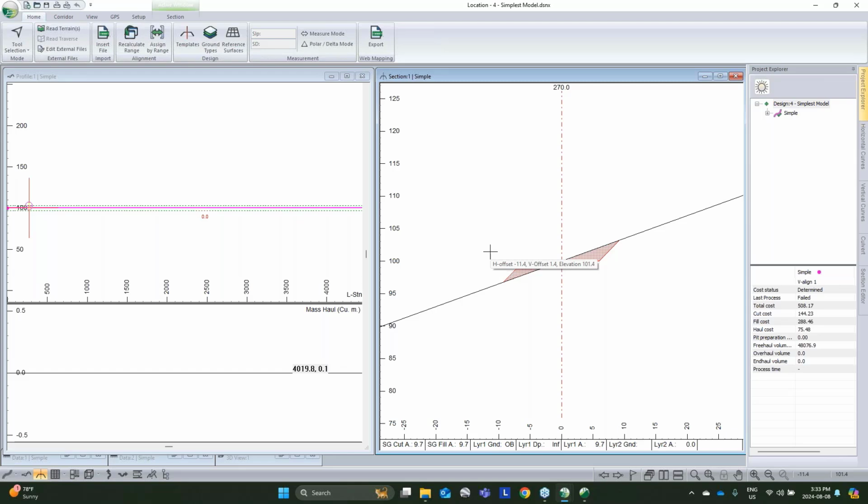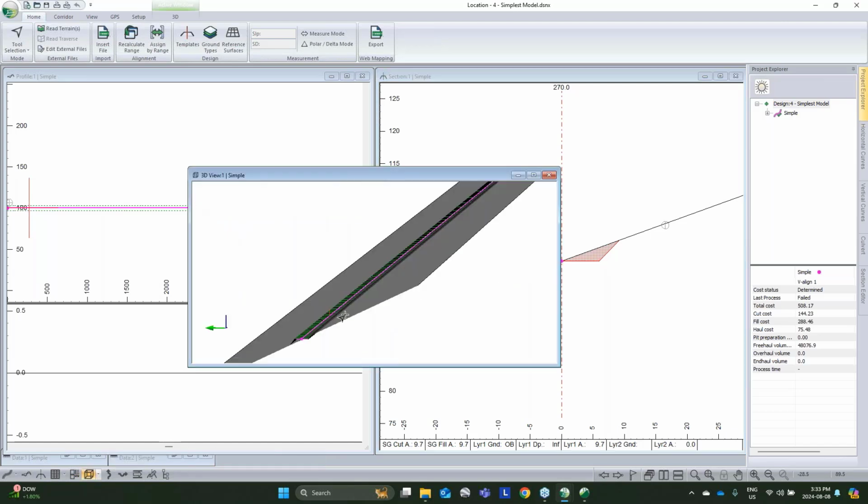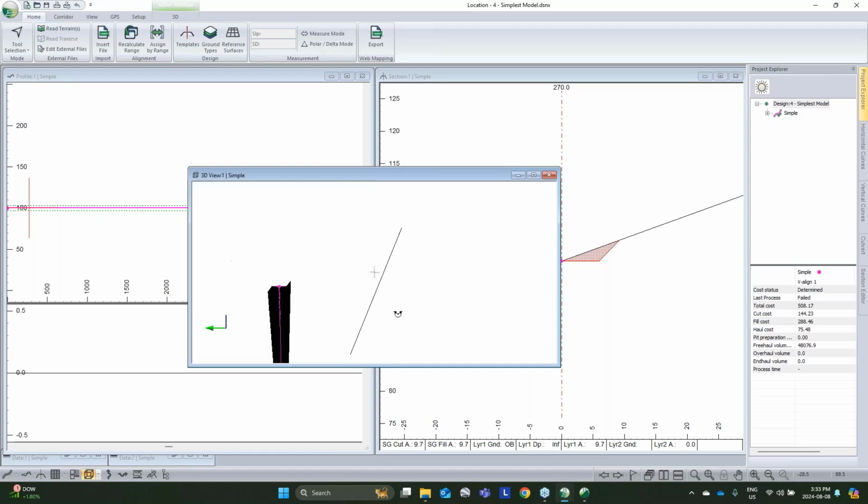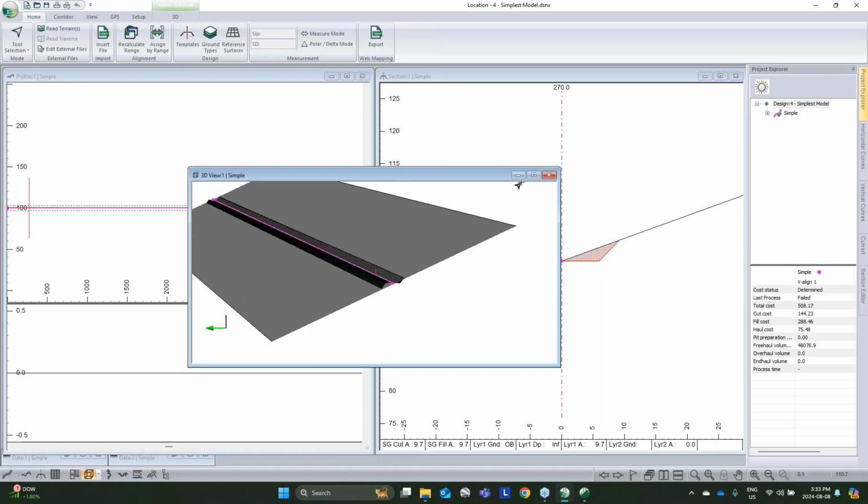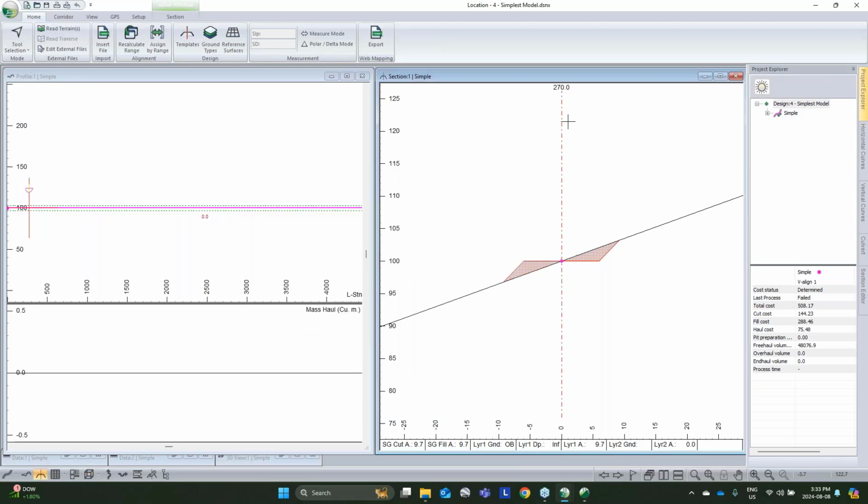So volumes, and here I'm going to deviate from having that real example that we were looking at to something that is super, super simple. And that is, how does this look if we've got just a flat terrain and a really simple cross section? Well, I've got my cross section on my topo surface, and I can just go in here and click measure, and we can go across here and we'll see that, oh, I clicked in a bad spot, but we'll be close enough.